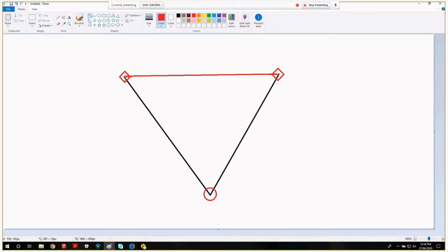So when we're making an assessment of our network adjustments, this shows incorrectly as more degrees of freedom, so more redundancy in the network. So the practice is to remove these, and whether you choose to remove this one or this one or this one doesn't particularly matter with GPS. One of the things you might look for is better results in the baseline processing, and you could assess which ones you keep from that. The easy way of doing it is just looking at what the longest baselines are.